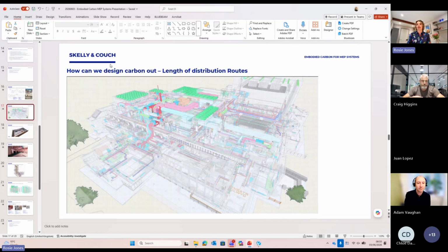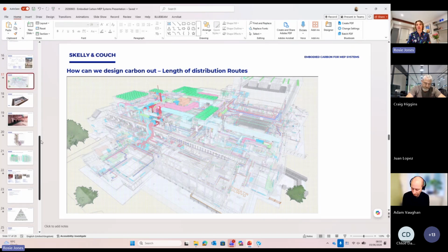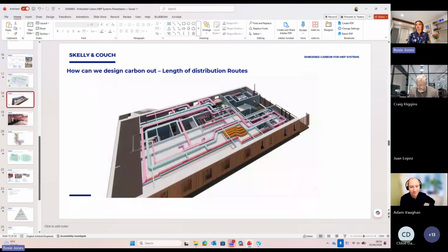And then the next few diagrams are ones my office's BIM team got quite involved and excited about, to demonstrate the extent of the building services within the building. So it gives us the scope for what we can minimize. All of these pink and blue are ventilation systems. Let's try and get rid of those by using natural ventilation systems. And these pipes are always on flow and returns, so if you can give it a central hub, then we're reducing those pipework runs.